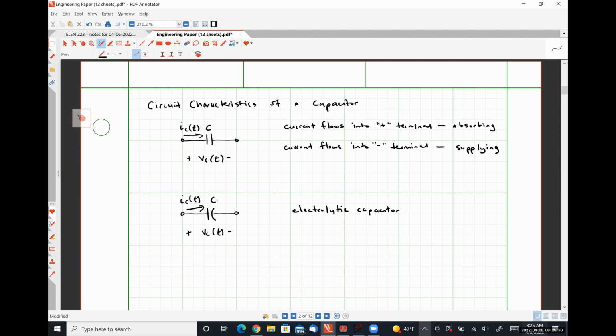But electrolytic capacitors are used in a wide variety of electronics applications. For those of you that go further into this and start designing things, you will have to pay attention to the polarity of your components from time to time. Electrolytic capacitors have a longer leg to denote their polarity. Physically, they're typically in a canister-like cylindrical package, and it has a picture of the schematic symbol on that packaging to let you know what type it is.